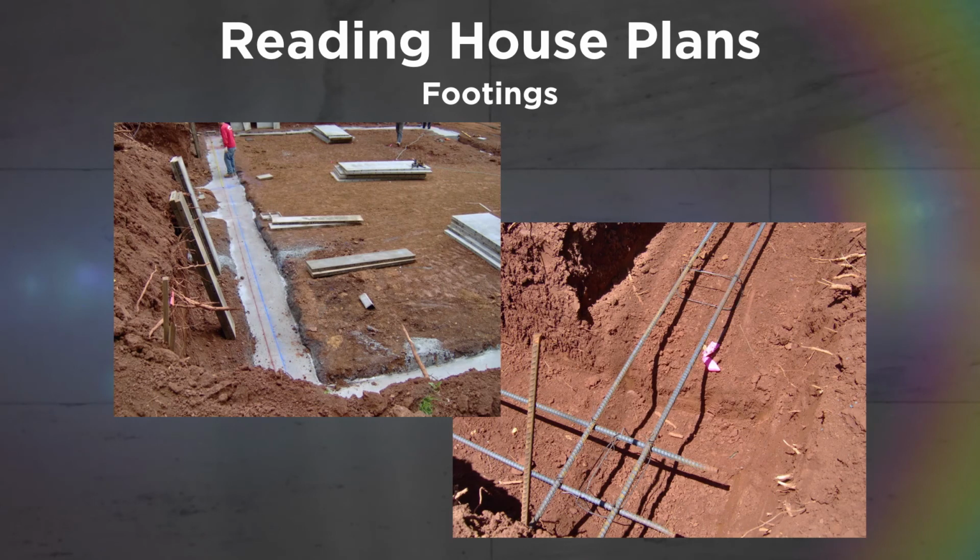Here's an example of how the footings are laid out and reinforced. In this warmer climate, the footing is not as deep and rebar is used to add strength to the footing. After the rebar is in place and lifted slightly off of the base of the trench, concrete will be poured into the trenches. The finished footing for this project is on the left.